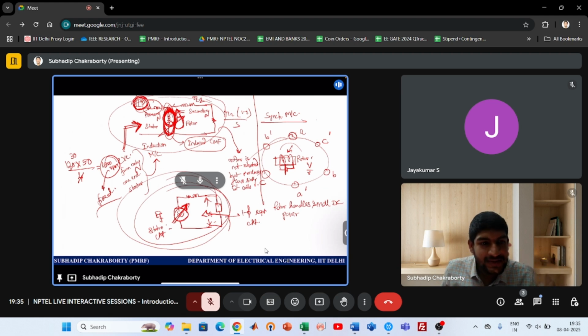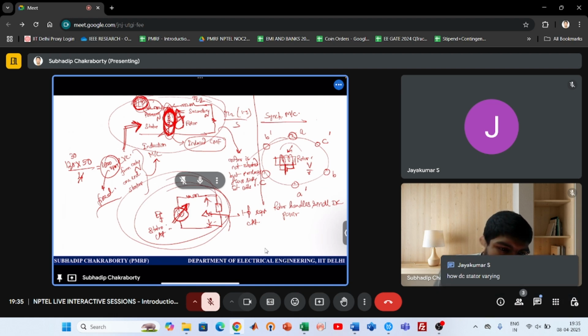But as the load keeps on changing, I want to also control the power factor. Then I have to vary, again, the power angle or the EF. So we'll see all the phasor diagrams, don't worry. But please understand, rotor DC, pure DC. Rotor only has the job of producing some controlled flux. More flux becomes more reactive power. Less flux, lesser reactive power, right? Because it is generating voltage support.